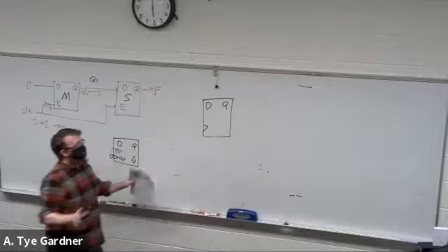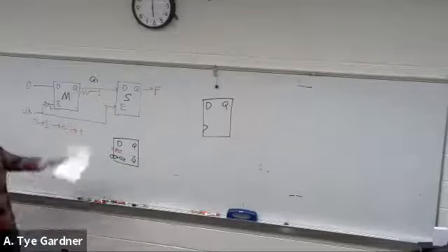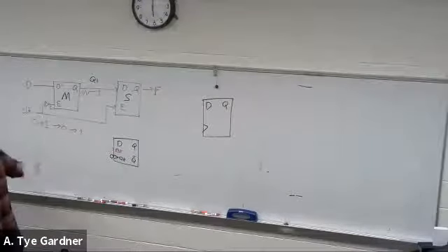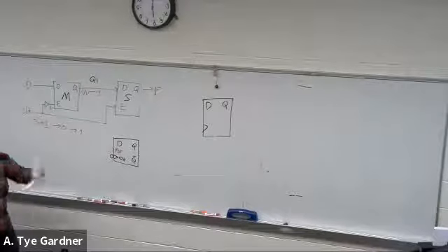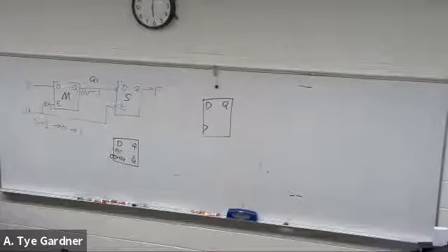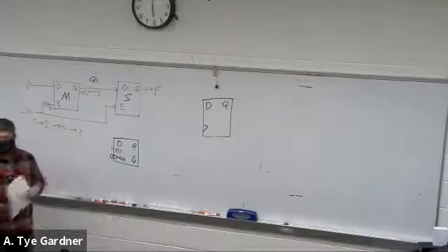This is the simplest way you can draw a DQ flip-flop, right? The triangle means that's where the clock plugs in. The D is where data goes in, Q is the output. I'm not going to draw a Q bar, we'll keep it nice and simple. So let's say I want an enable on this device.